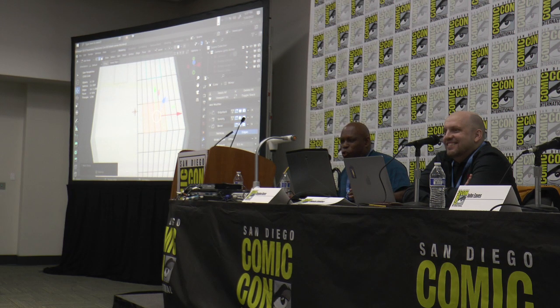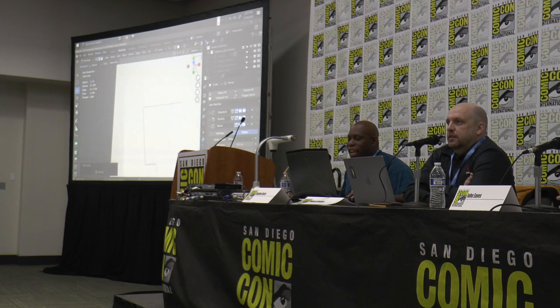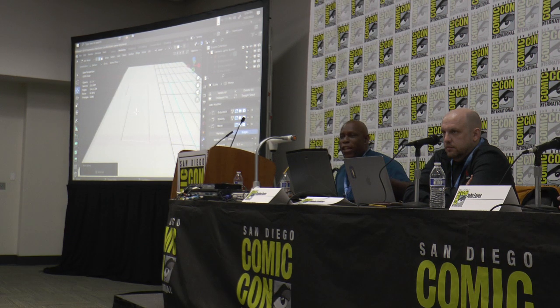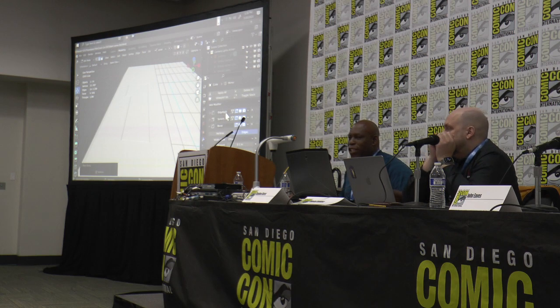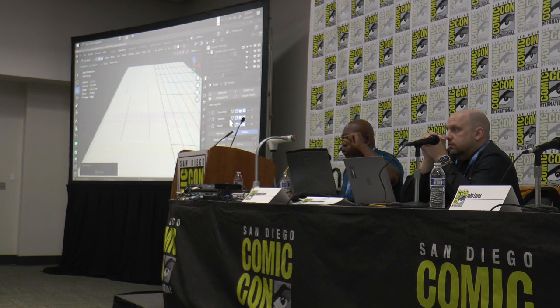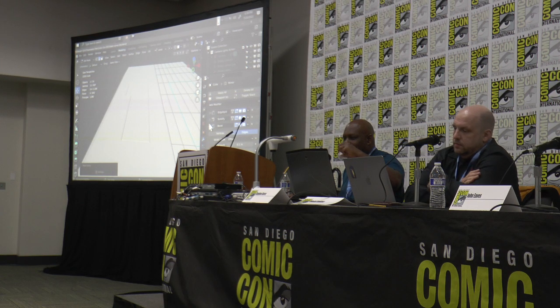Yes. So are the modifiers actually changing the geometry of your shape? Exactly. It's actually changing the geometry. It's creating extra bevels and faces. Look, edge split means split the edge. That's what edge split is doing. Solidify means make it a little thicker, because it's just a single thin face. And then bevel means bevel those edges. So that's what it's doing.